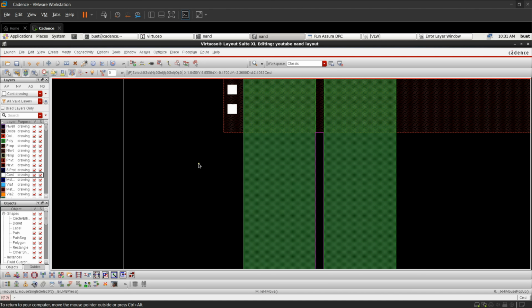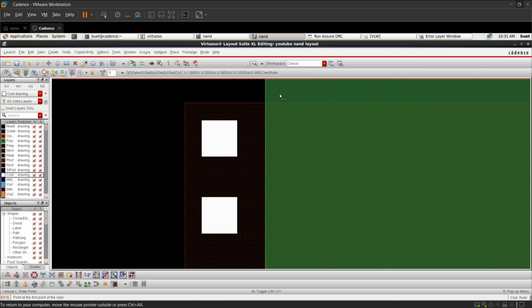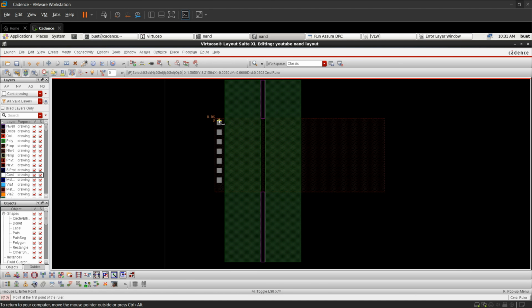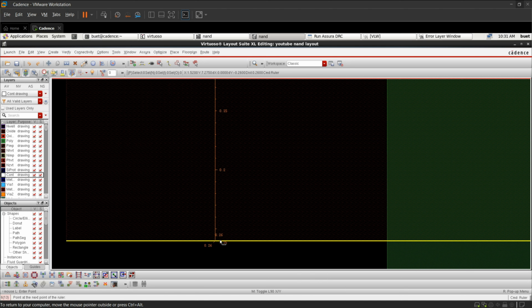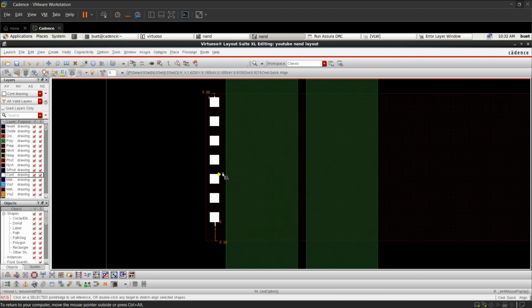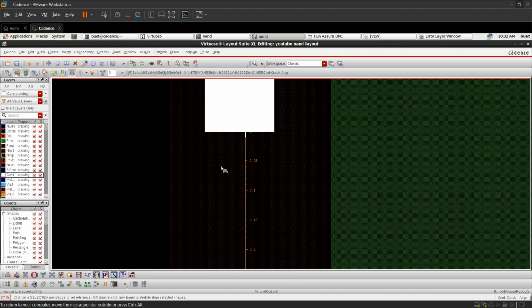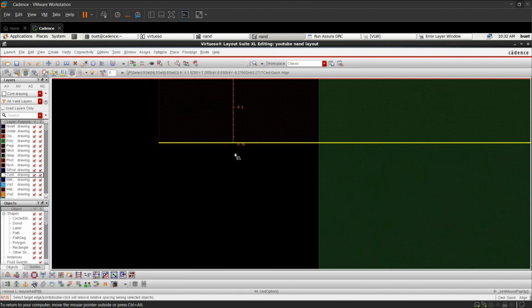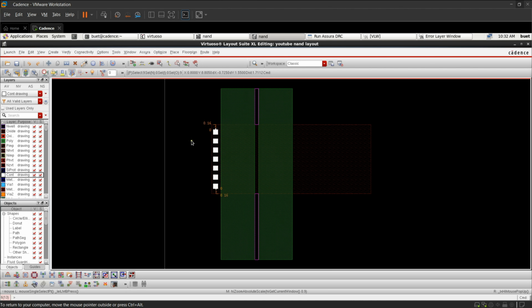These are the extra. In similar fashion we are supposed to do top side spacing and bottom side spacing the same. On the top side it is 0.26, it should be 0.16 for each side. Select these entire contacts, press A, right click, make it 0.16, hide, select this edge with respect to this. Yeah, it is 0.16. Right now it is symmetric.